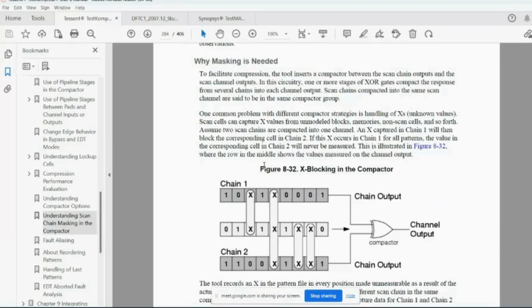And we have two channels, each channel holding 100 chains. Now we have a total of 200 subchains. If you want to trace a circuit with 200 subchains and find in which chain the failure is on the tester, it is very difficult. In our environment, we can do some simulation debug and all, but in real time we cannot.